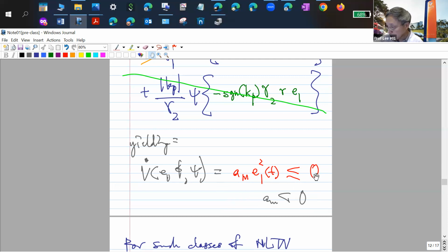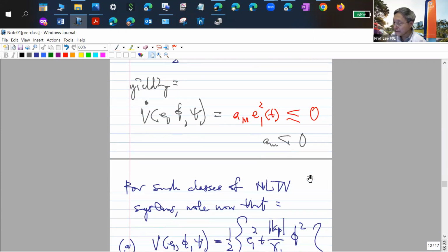So what you're now getting is that the ellipsoid has a time development, and it develops such that V dot is always less than or equal to 0. And we're not done, because you really have to do your signals and systems very carefully for these things. A lot of times, even people who did adaptive control for research reach this stage and think they are done. They are not. Because you really now need to go on to look carefully at this.